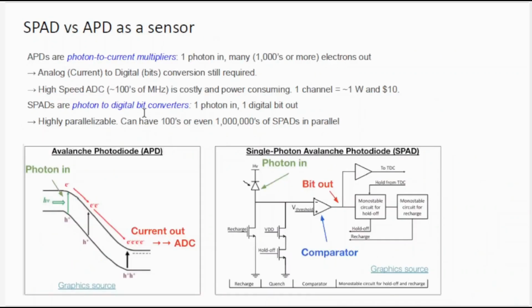One thing I thought was worth noting is you will find if you go to LiDAR systems, for example, they'll generally use APDs. They won't use SPADs. I think that's probably the one difference. You can use just an APD instead of a SPAD. The biggest difference is it's just not practical for consumer electronic systems. APDs are expensive. You're doing an analog conversion. There's power involved, etc. So I think a SPAD makes much more sense for consumer electronics systems.